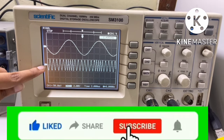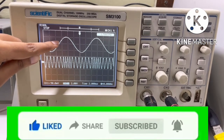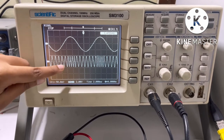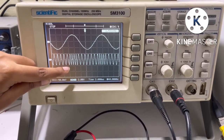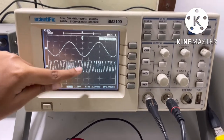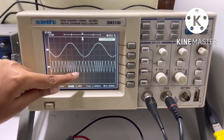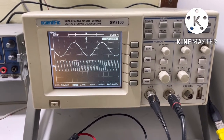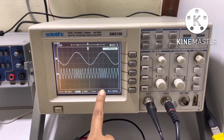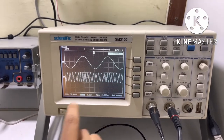As we can observe, during the positive half cycle of the message signal, the carrier wave is compressed, that is, the frequency has increased, and during the negative half cycle of the message signal, the carrier wave has expanded, that is, the frequency has decreased. So we can say that the frequency of the modulated wave changes in accordance with the message signal.